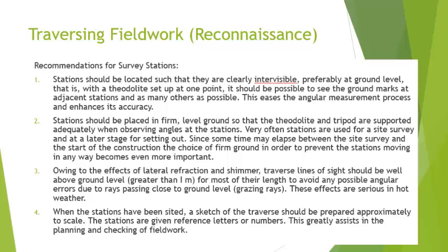And the sketching process is highly recommended to be as close as possible to the correct measurement. And a number is given to the stations. Although it seems to be a very simple process, without proper and thorough reconnaissance, it can affect the accuracies and overall survey costs.